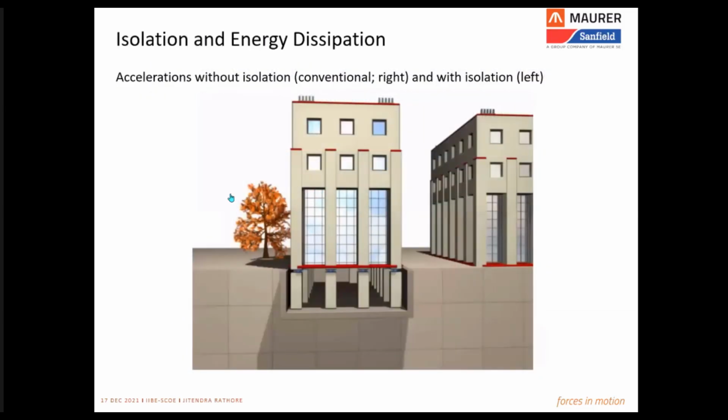So that was a brief about the main challenges in front of a bridge bearing, and the improvements and advancements that have been made so far to overcome those limitations and challenges and to improve the service life and durability of the bearings. Now, as I said in the beginning of the presentation, we are no longer calling them just bridge bearings, because they are now finding applications in bridge structures and building structures equally. This application we call isolation bearings.